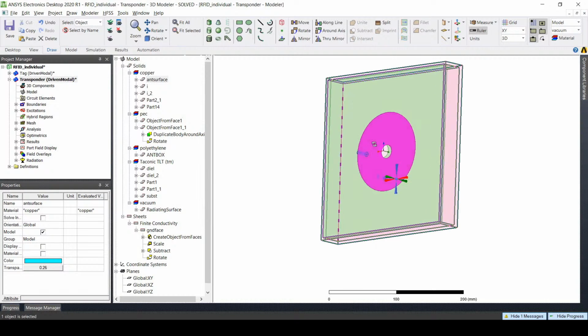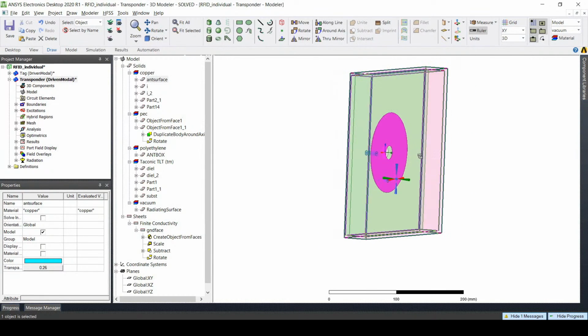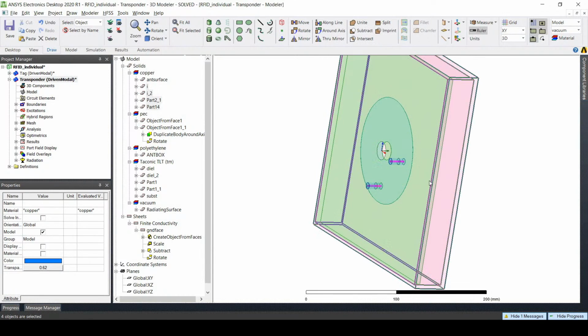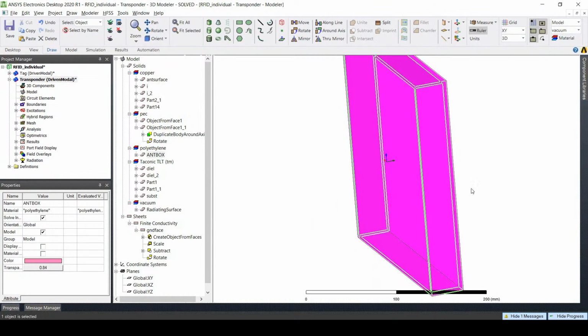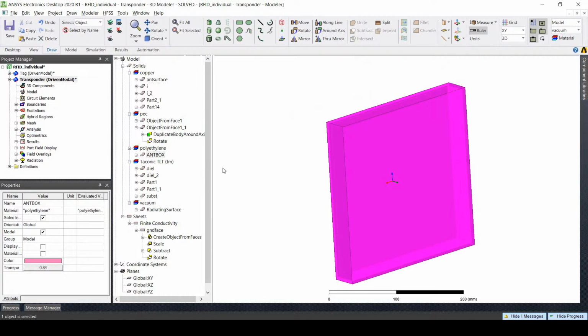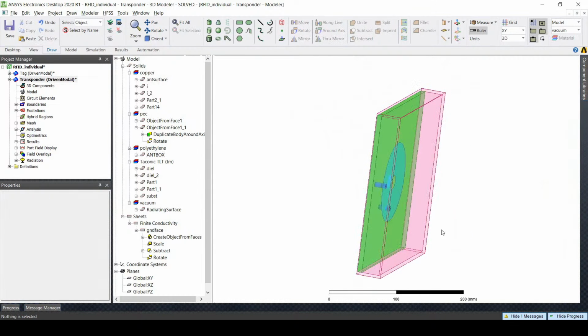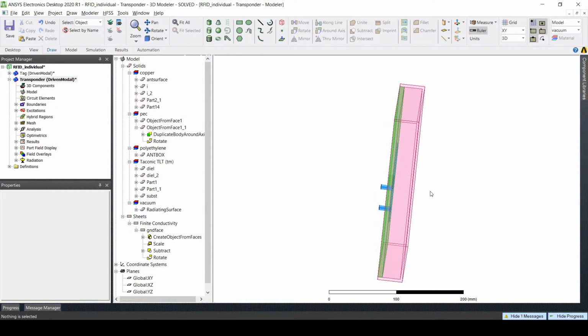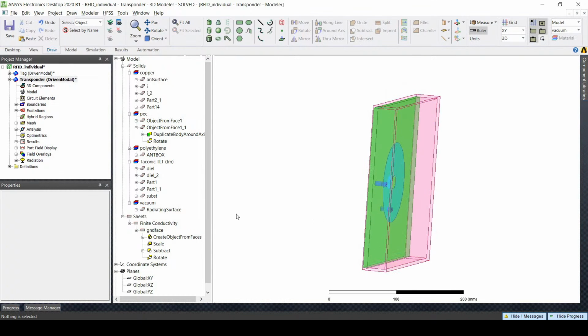Here you can see our antenna surface is copper, and this part is the copper wire that excites our antenna. And for the enclosure, we have it as a plastic material. This ensures that the enclosure doesn't affect our radiation pattern by a lot.